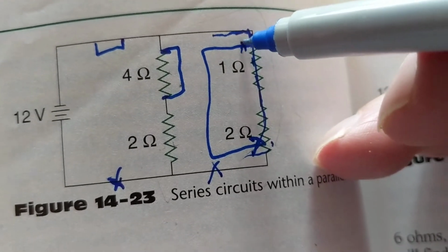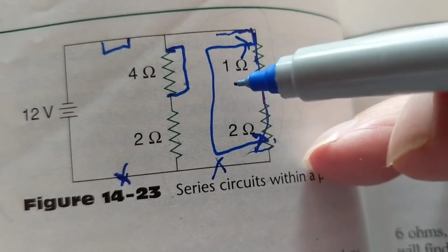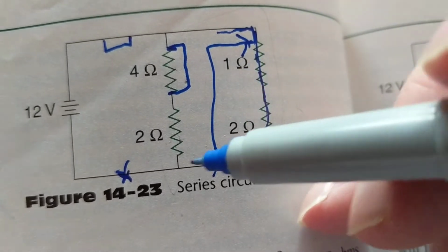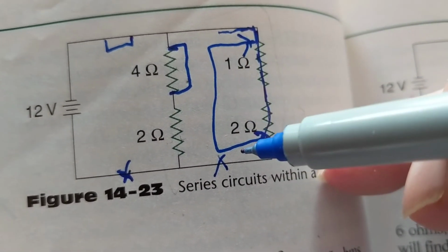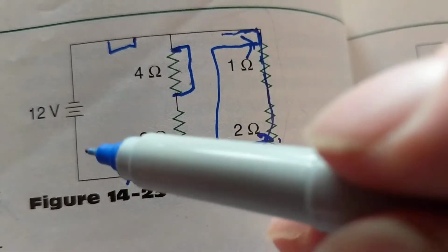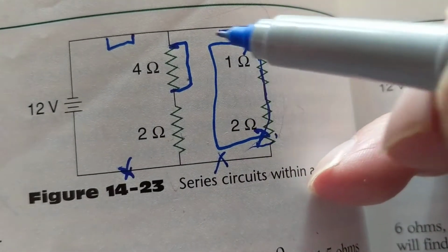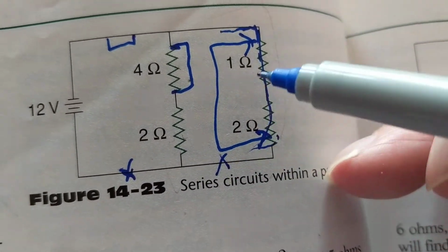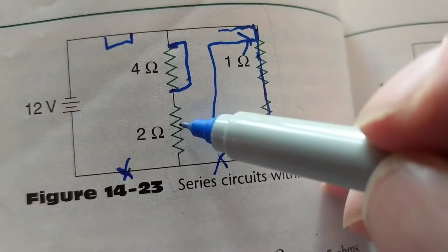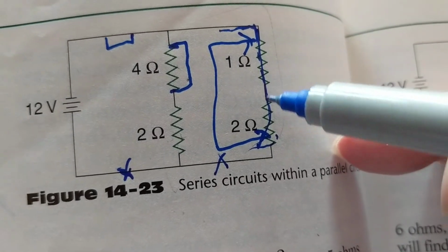Sorry, I couldn't draw it better, but I think hopefully you understand. We have a short across these two. Now what happens, you think? Trouble. We just shorted out the battery. What did we say? Current wants the path of least amount of resistance. Which path here, this branch or this branch, has the least amount of resistance?